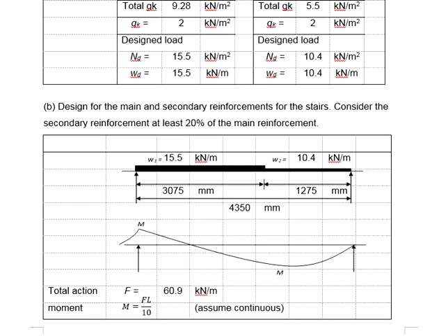The calculation is relatively simple. Whatever the shape of the bending moment diagram, which indicates that there are negative moments and positive moments, regardless of whether negative or positive, a moment of FL per 10 is assumed.